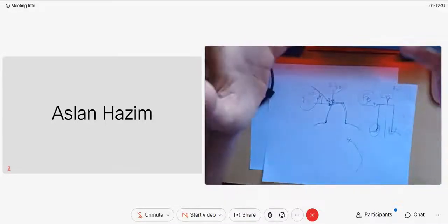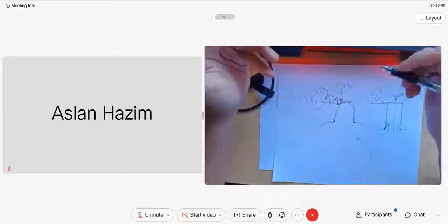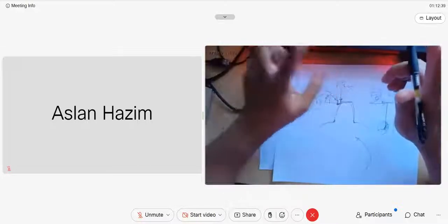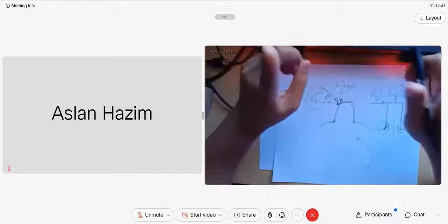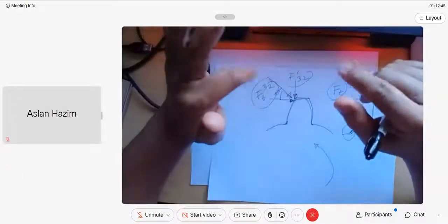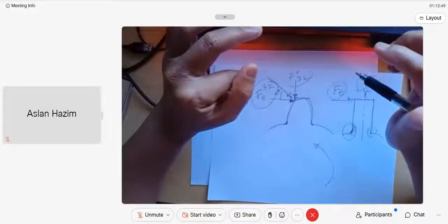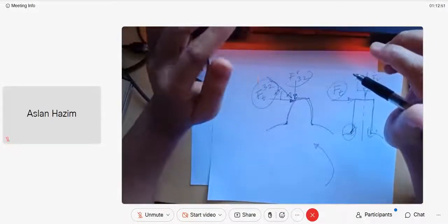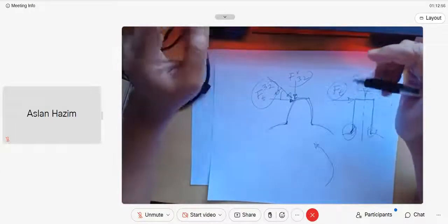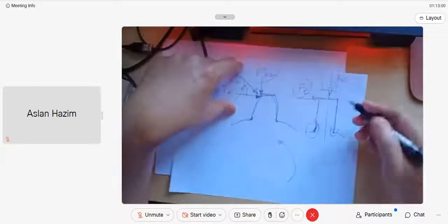If we have force, we have stress. In gears, we have two sections. First is bending stress, for today's lecture. In the second lecture, we will go on to surface stress, which I will explain later. But today, we focus on the bending stress acting on the gear. The bending stress caused on the gear tooth is from your F tangent, so assume it like this cantilever with F tangent.